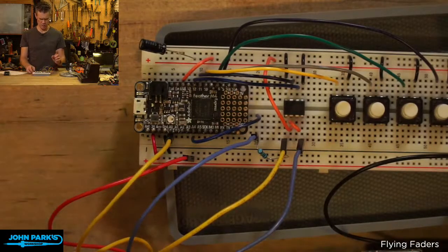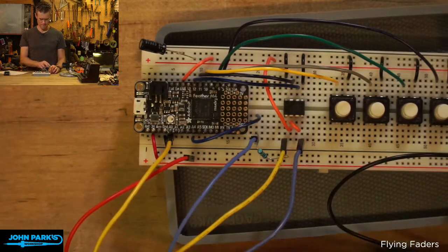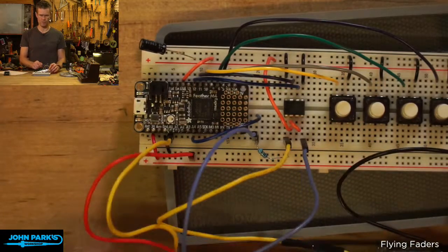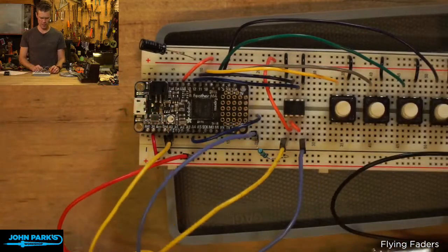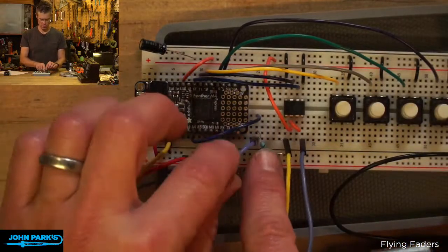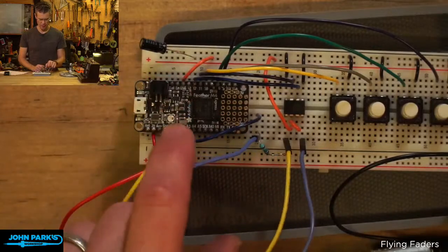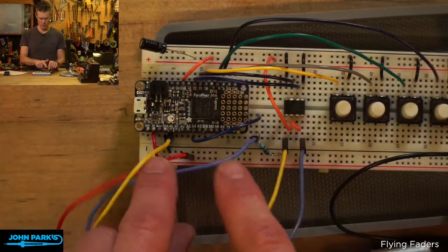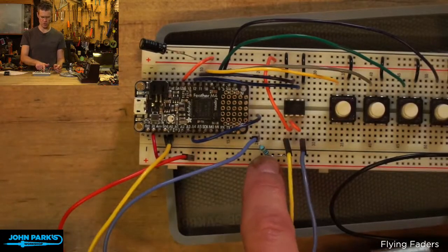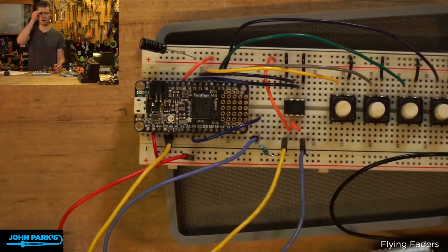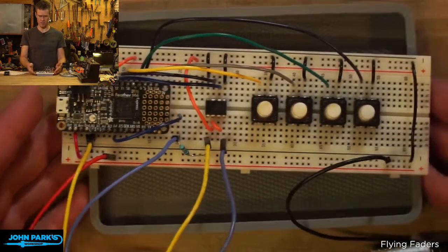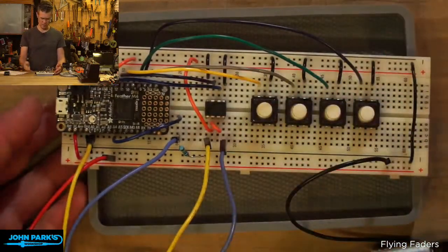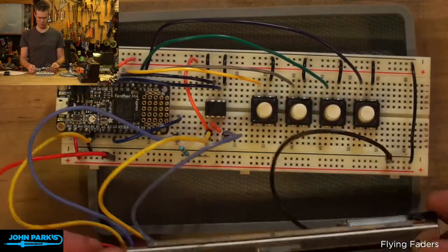And then the last thing is the blue wire you see here coming off of the touch pin. I have it going onto the breadboard, and then I'm running it to a touch pin. A4 is what I'm using. I'm also running a 1 mega ohm resistor to ground, and that is necessary, in most cases, for the capacitive touch to work. Then the last thing I've got is some buttons here that I'm using just to save, to play back some presets of position on here.